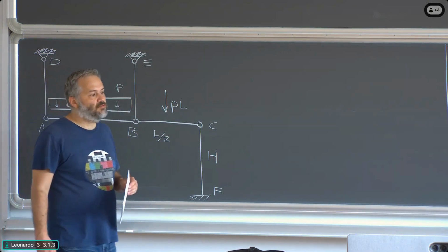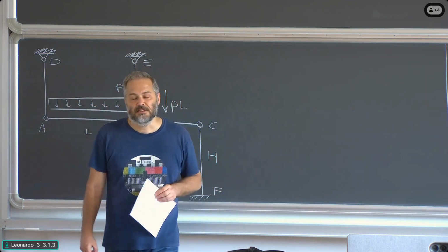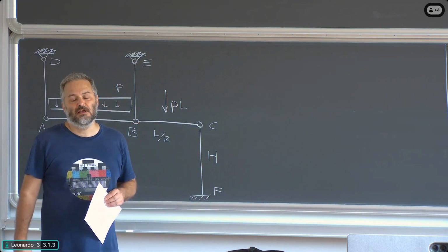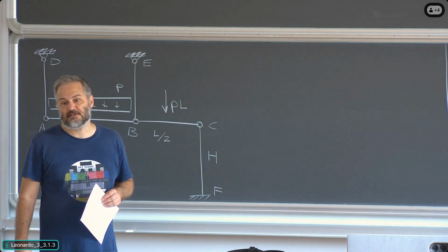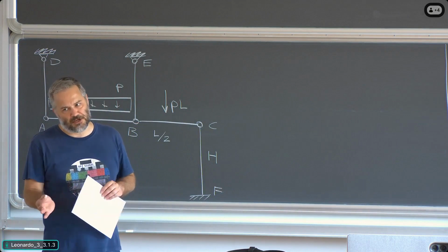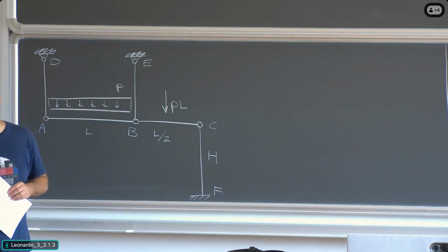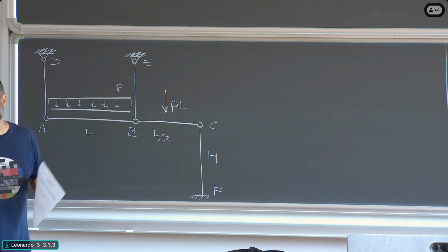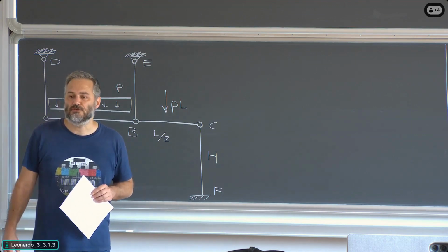Now, how do we start with the structural analysis? First of all, it is wise to look if we can find anywhere in the structure some truss members, which means members that are subjected only to an axial force, be it tension or compression. How do we find the truss members? Basically, a member is a truss member if it fulfills what I call the 3 golden rules.